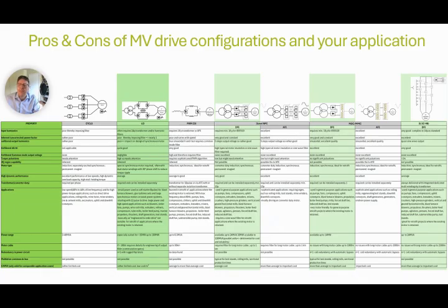While the PWM CSI, the MMC and also the 2-level series Cascaded H-bridge can drive a standard motor, ideal for retrofit applications, the 3-level neutral point clamped will require a sine wave filter or a dU/dt filter for reliable operation.